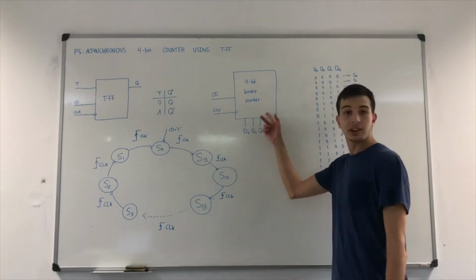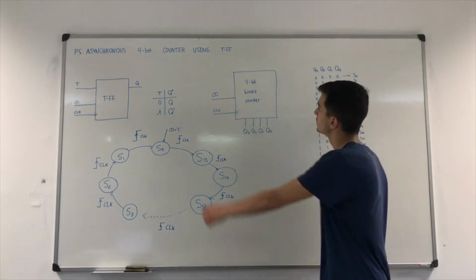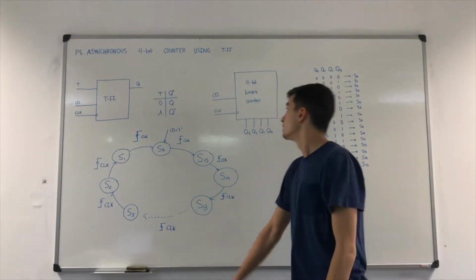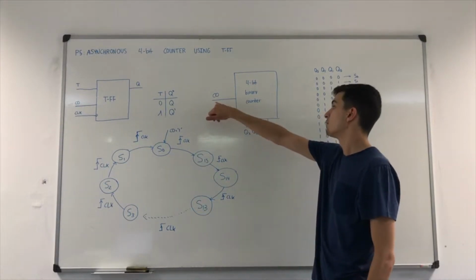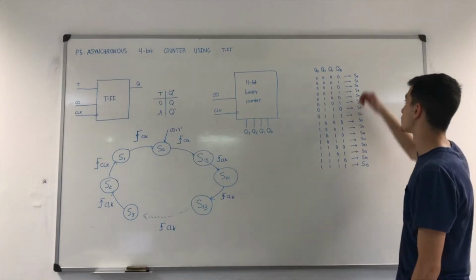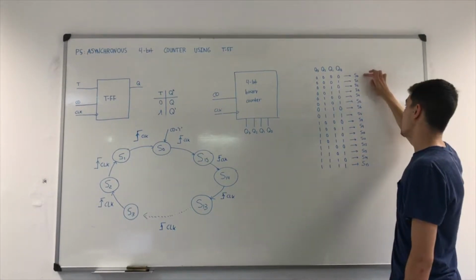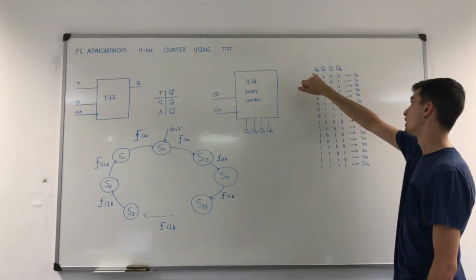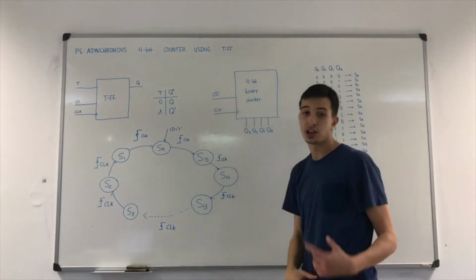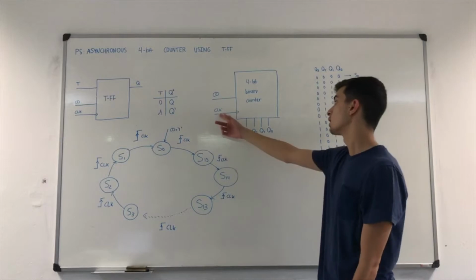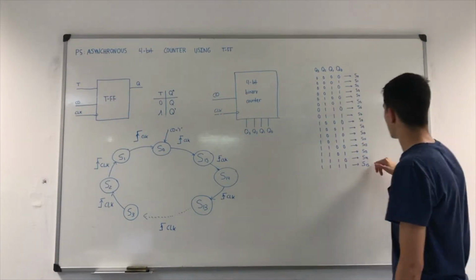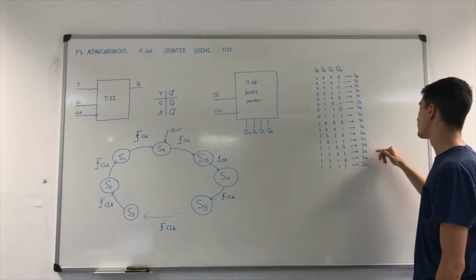As we can see here, analyzing the symbol, the system doesn't have reversibility and neither counting enable. This is because when the clear direct is equal to 1, the initial state corresponds to S0 and the outputs are 0, 0, 0, 0. But to change the state, we have the clock. With the rising edge of the clock, we can decrease the state.